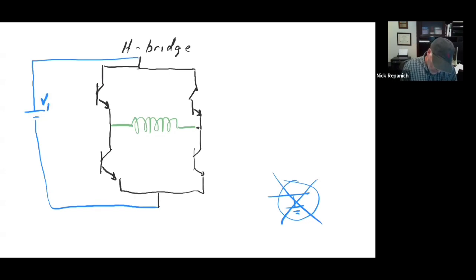So this is V bus. And generally the bus voltage is different than VCC. Bus voltage means, oh, that's our 600 volts DC that we're going to put to that motor. That's the high voltage. Now, the reason it's high voltage is because we're running an inductor. So what's an H-bridge do? There's one key thing that an H-bridge allows us to do with the motor.